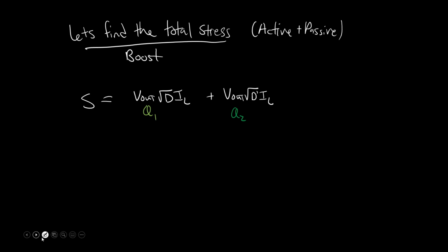However, if we look at the utilization instead, which is really V out times I out over S, then we can find something that's a little bit more comparable, right? So again, this isn't the real utilization as defined in Fundamentals of Power Electronics because we're looking at both switches and both of them may not be active. However, this is just an exercise, right? If you were to use two active switches, then this would be the stress of this boost converter. So V out times I out, that's our output power.